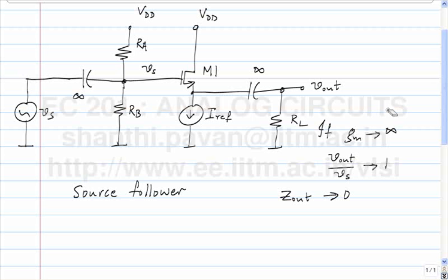the gate drain voltage as a function of time. And why is it varying as a function of time? Because the input is varying in a sinusoidal fashion. And we need to find the total current in the transistor. To figure out the limit for triode operation, we are interested in the gate drain potential. To figure out the limit for cutoff, we are interested in the total current or the drain current of the transistor. In either case, for the limits of large signal operation, we are interested in the total voltages and total currents through the MOS transistor.